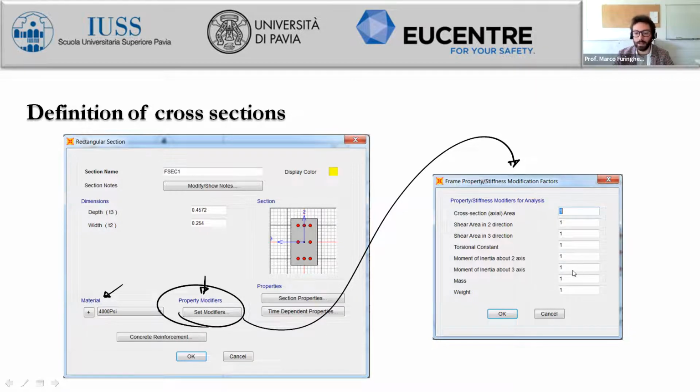so 10,000 and 10,000 here. So this means that we are modeling a Timoshenko beam, but with a very amplified moment of inertia. Sorry, not moment of inertia, the shear area. The moment of inertia is actually what we are going to model. The shear area 10 to the 4th, 10 to the 4th. So we are amplifying the shear area, so automatically we can say that the shear stiffness is approximately infinite, and this is approximately equivalent to the Bernoulli theory.